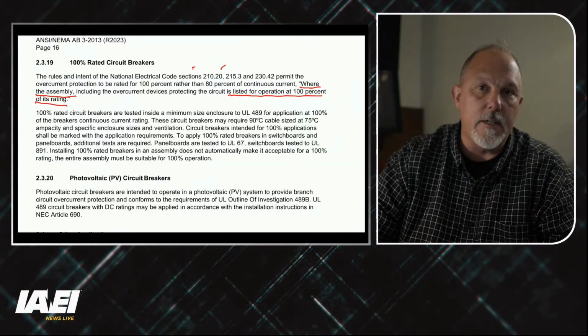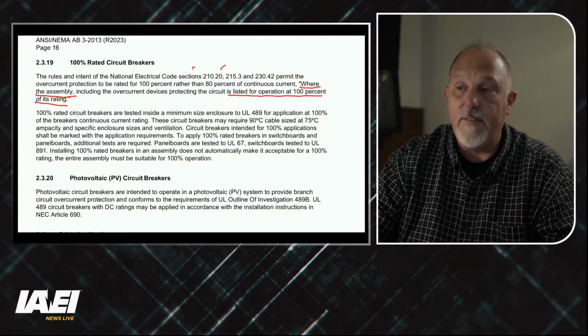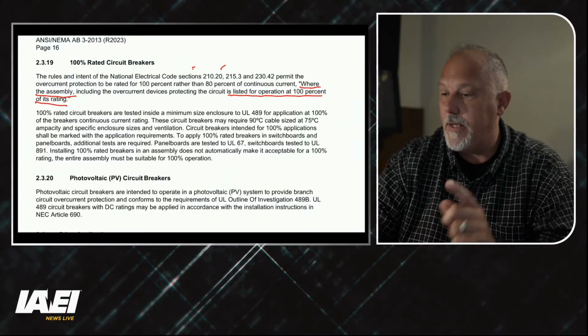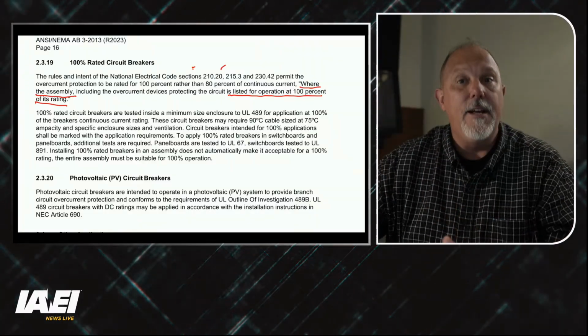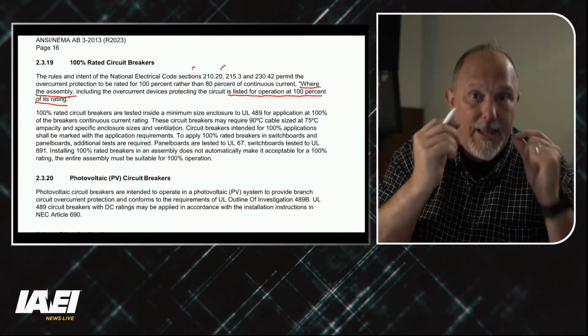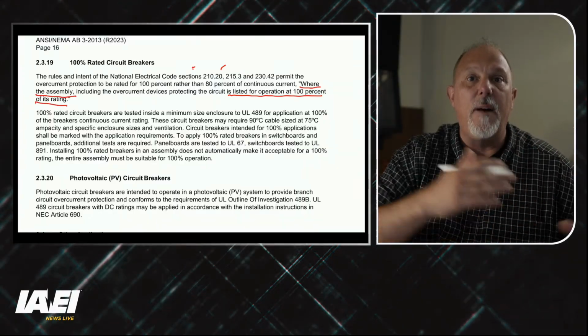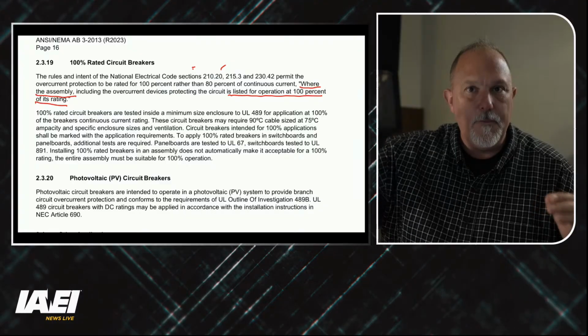If I put too small of a conductor on the lines and lugs of an overcurrent protected device outside of how it's tested, that would be ungood, all right? So unless it's 100% rated. Now, if it's 100% rated, maybe, just maybe, the high density copper of the bus compensates for increasing the conductor size, right?